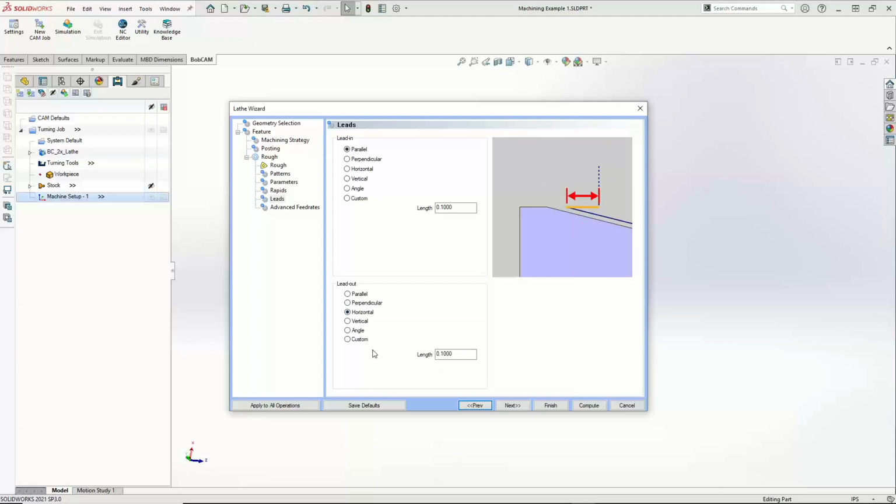We've already extended this. If you remember from the beginning of this, I think I did a 1/4 inch at the beginning and an 1/8 inch past center. So I'm going to go an 1/8 inch past center, knock down any tit that's going to be left there, and then come straight off the part in the Z axis. That's fine with me. So when we're done with that, we'll hit next.